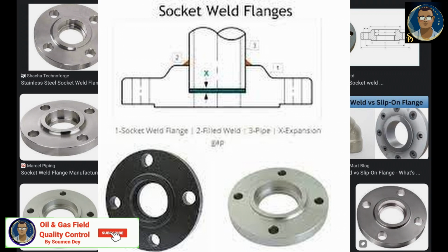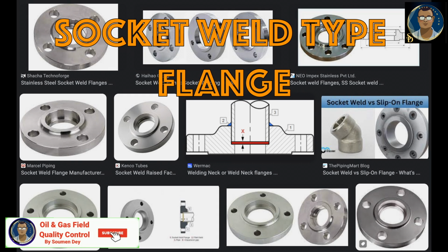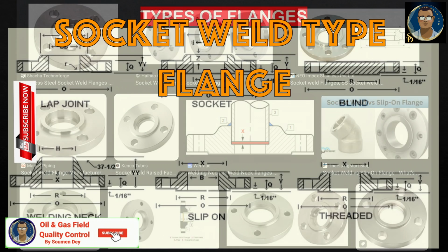This practice was originally employed to reduce cracking during thermal stresses in stainless steel superheaters. But over the years, it has become standard practice for the installation of all socket weld flanges, even socket welded joints. Socket weld flanges are available in pressure from 150 psi, and pipe schedule 40 to schedule 160.